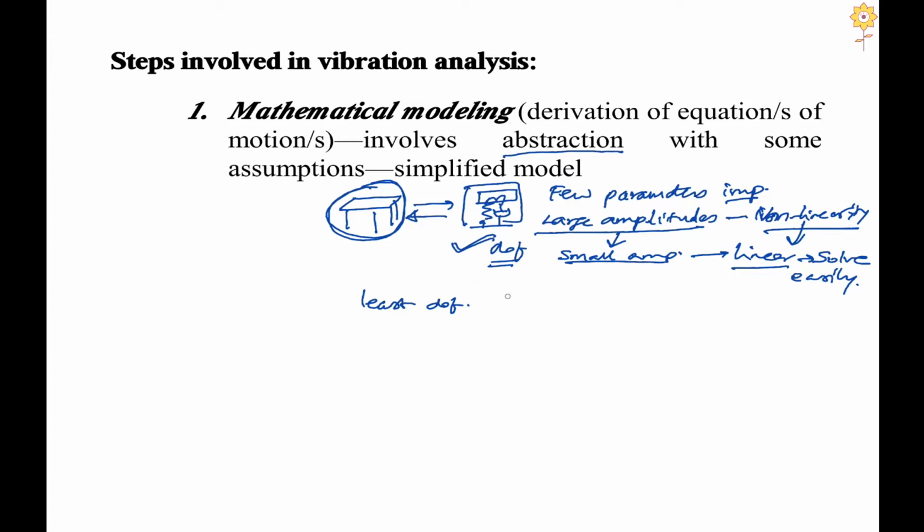So what is the advantage in this one? What is the advantage? So when I solve this, I get some value of omega n, right, and this will be very crude, or there will be a lot of error involved, but I get a decent approximation, or a fair idea of the range of the lowest omega n. In this case, I am having only 1 degree of freedom in the schematic model, so I will expect only one value of omega n.